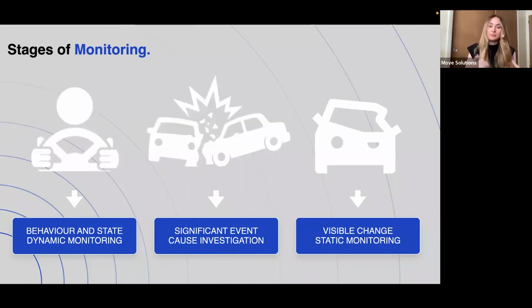So with our monitoring, we're monitoring the behavior and state. We're monitoring the vibrations and accelerations and understanding if there's a change in the structure before you would pick it up on, say, a total station, or if you have a tilt meter on the structure. You're able to understand that there's a change happening in that structure before you start to see that physical damage.